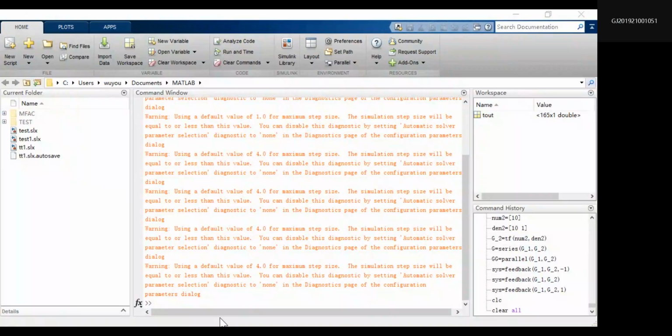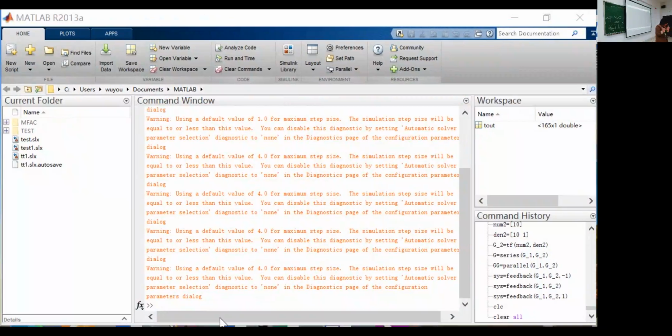So here is what you need to control the system. You need to adjust the parameter of the controller. And here the gain block is a controller. From this simulation we can read the message: if you want to control a system like this, using just one gain as the controller is not enough. It can adjust the overshoot, but it cannot ensure accuracy. So maybe you need to choose a more complicated controller.